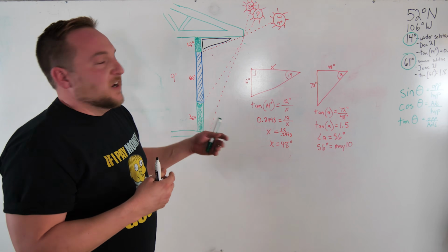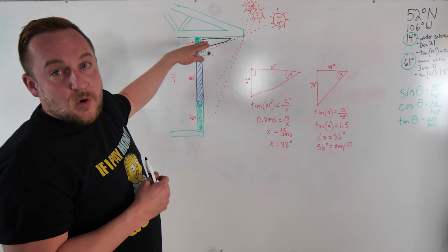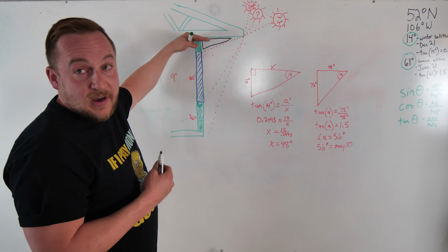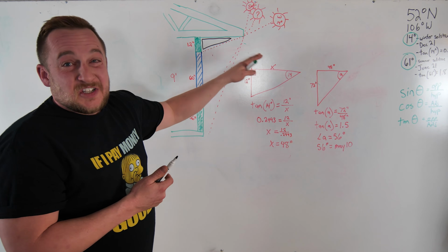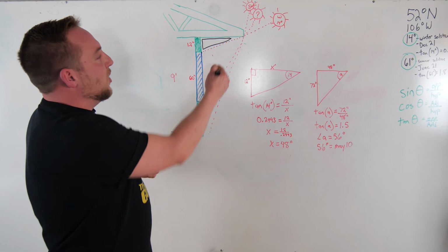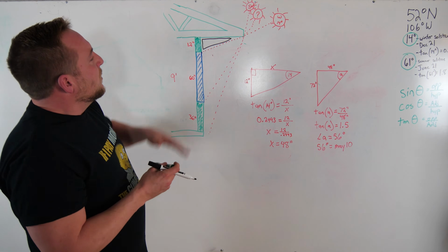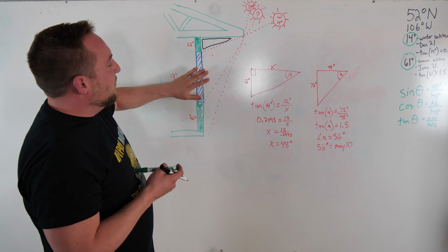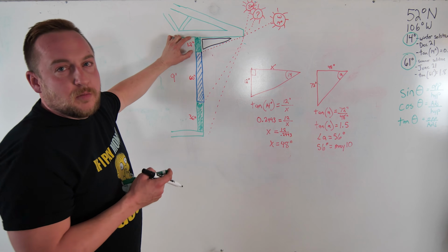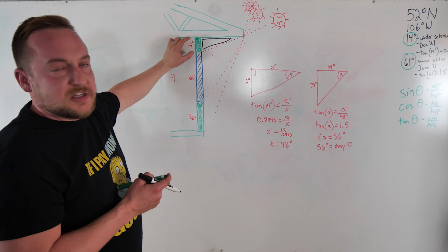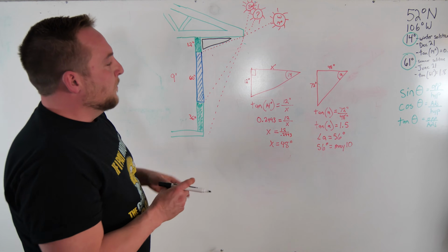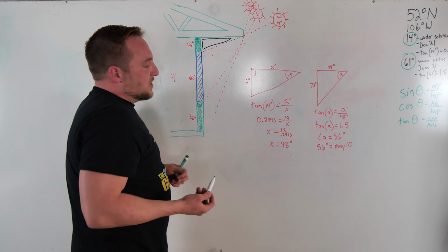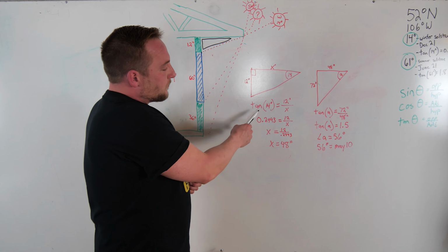But in order to find out the eave overhang we need on the house or any building, we need to know one constant side. So what is my constant on this? Well, my trusses go this way, and you have glazing, and I have a structural beam above the window. So there's a constant that we have: 12 inches is my beam above the window. Let's input 12 inches, and this is how you calculate it.